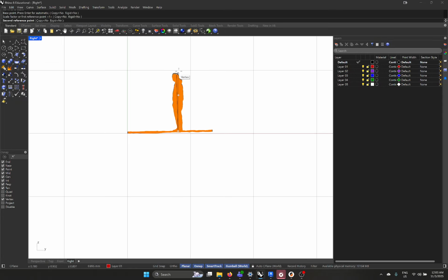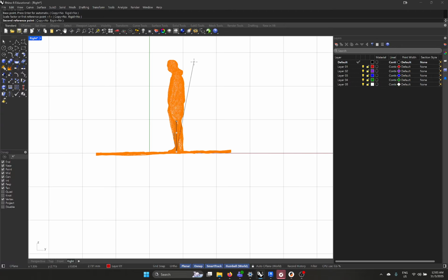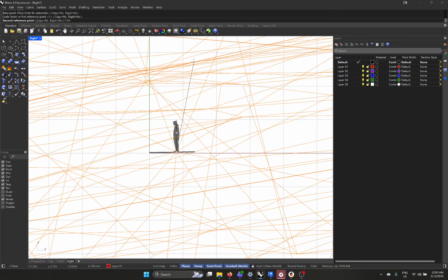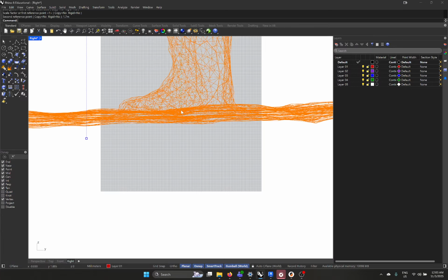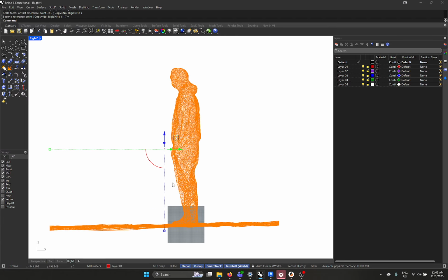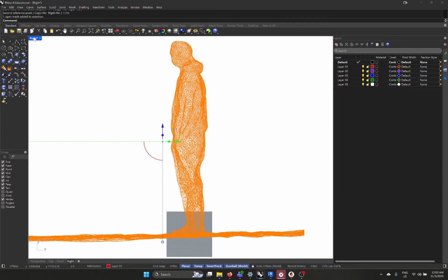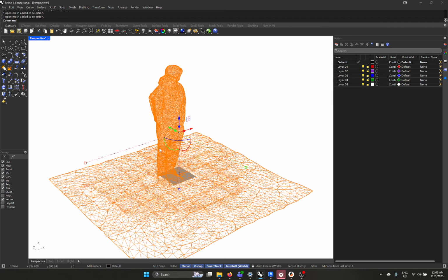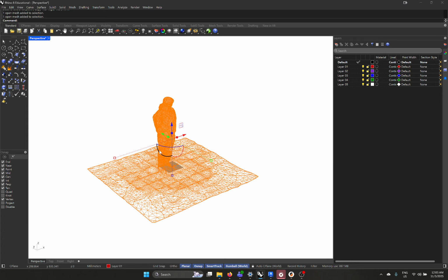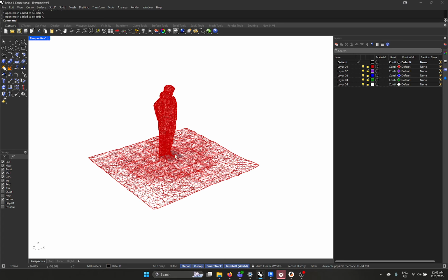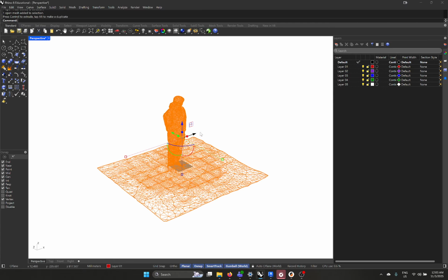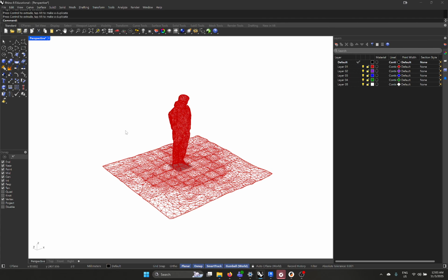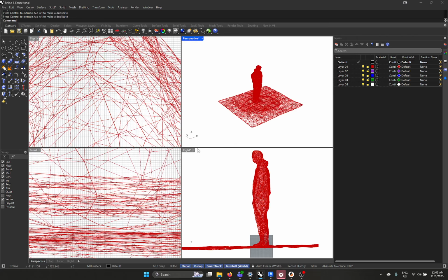We'll do something like, well, we want to maybe measure our subject, right? So let's say this person that was 3D scanned stands at about 1.7 meters tall. I'm going to type 1.7 meters from that scale command. Then now I've got my model at the correct scale. And then what we'll want to do here is just double check that we've got indeed the right height.